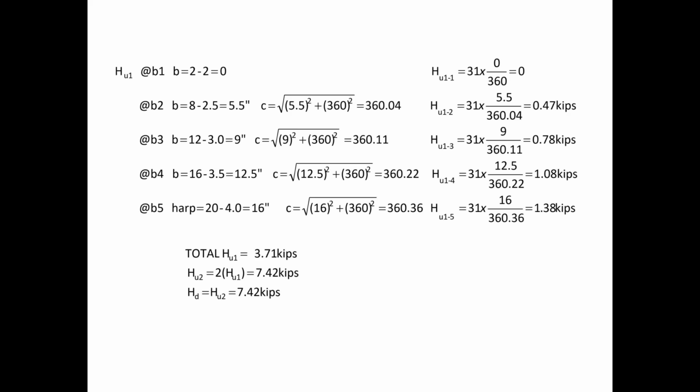Are the hold-up columns on the outside of the bed? Usually they're sitting on the soffit of the bed. They're sitting on the same surface that casts the bottom of the beam. It's just that they're sitting between beams, so they're not cast in concrete.